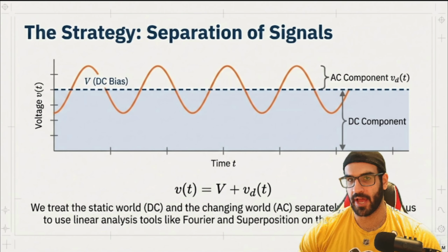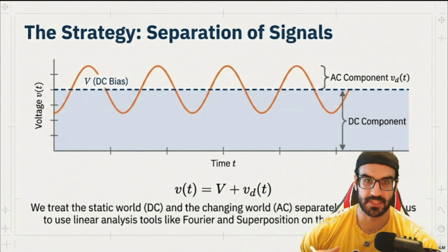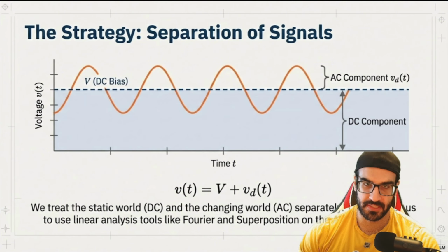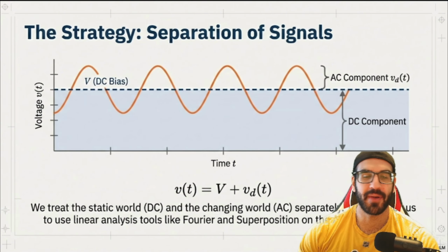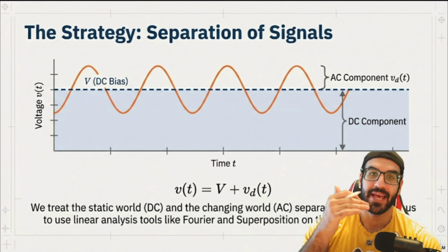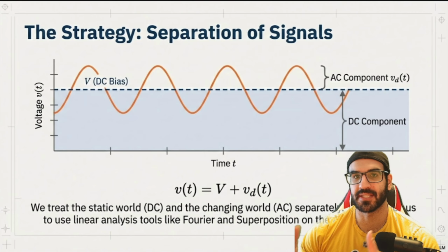So, before talking about the nonlinearity and any formulas related to that, let's touch on this point: in real life, not all signals are going to be either AC or DC. At some points, we have a combination of those. AC by itself we know. But the DC, when it is combined with AC, is something we call bias. The voltage bias, maybe you all heard about that, is the DC part of an AC voltage. It means that it has the responsibility to move a sine wave, for example the AC sine wave, up or down, based on the value that it has.